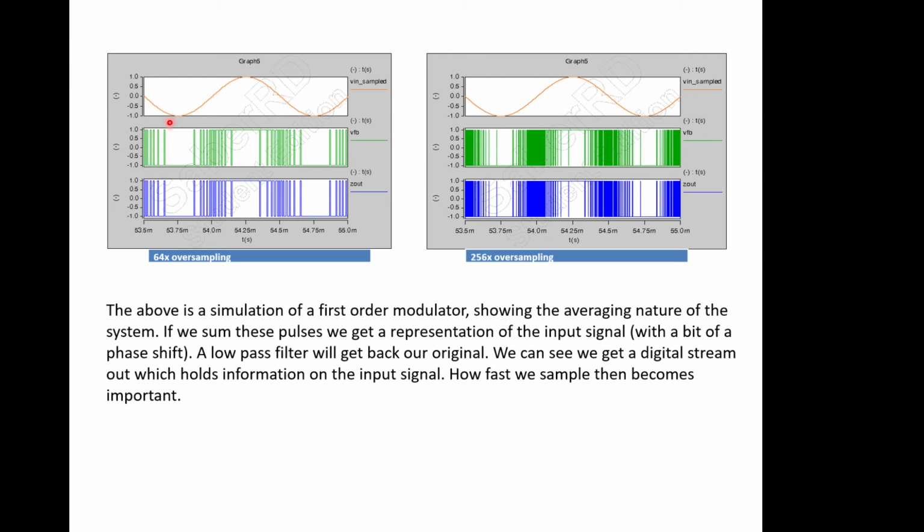And at low, negative levels, the output of our system tends to be quite low, and then as we get closer to the 0 crossing again, you can see we get a lot of crossing points, and then at the high point the output of our modulator starts to stick high, and then crosses over again. And you can see how this sine wave is encoded in the average level of this output. In fact, if we did low pass filter these pulse trains, we would get this signal back again, because the average of this is 0, the average of this is high, the average of this is 0, the average of this is low. So it's a pulse representation of the information, so you can see how it's encoded.